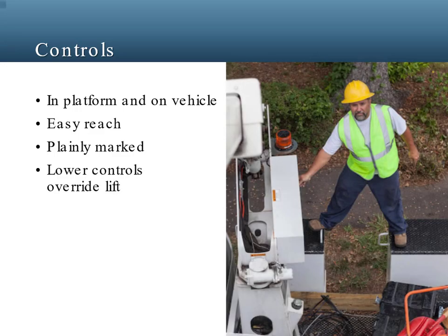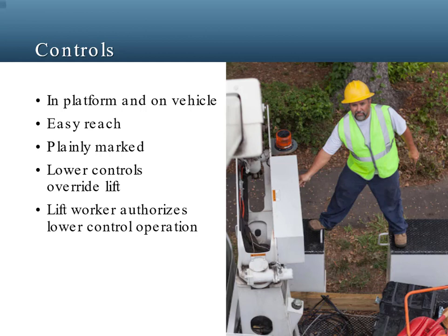The lower controls on the vehicle must be designed to be able to override the lift controls in case of an emergency in which the worker in the platform is unable to operate the lift controls. Except for emergencies, however, lower controls should only be operated with permission from the worker in the lift.